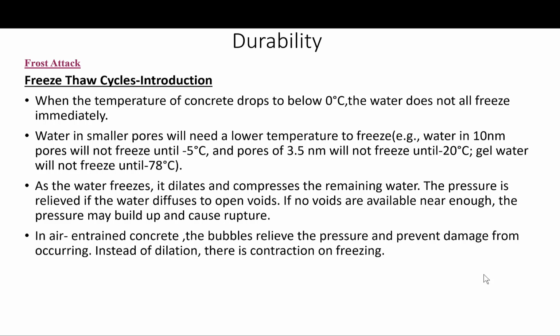For example, water in pores of 10 nanometer diameter will not freeze until 5 below 0 Celsius or 23 Fahrenheit. And in pores of 3.5 nanometers, water will not freeze until 20 below 0 Celsius or minus 4 Fahrenheit. Also, the presence of alkalis in pore water may result in a decrease in the freezing temperature on the order of another maybe 1 degree Celsius.